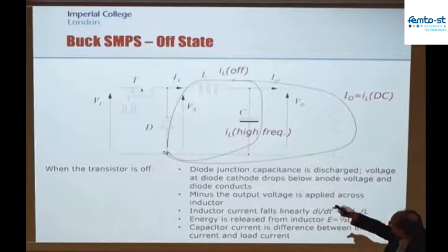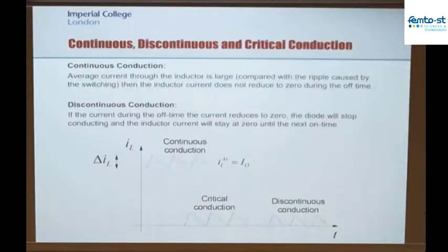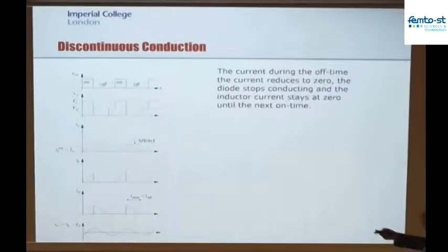So we were previously having, in continuous conduction, that point was purely defined as either being at Vin or being at ground. When we go into discontinuous mode, it's either at Vin, ground, or Vout. So when there's no current flowing in the inductor, that point there is going to be held at Vout, which is exactly what you see here.